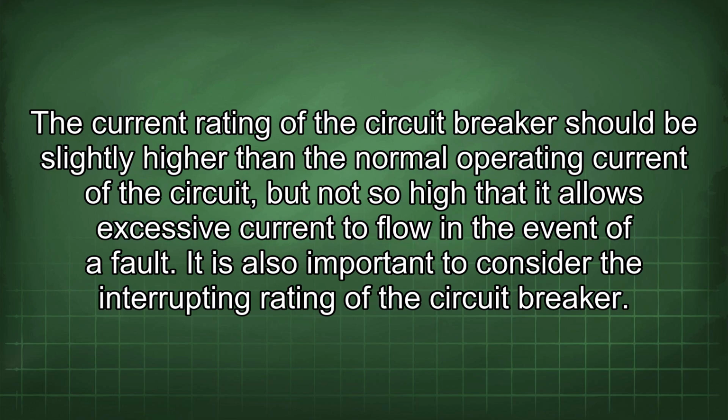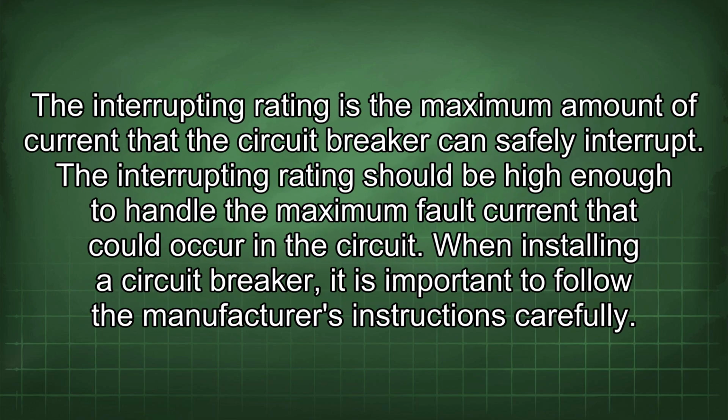It is also important to consider the interrupting rating of the circuit breaker. The interrupting rating is the maximum amount of current that the circuit breaker can safely interrupt. The interrupting rating should be high enough to handle the maximum fault current that could occur in the circuit.